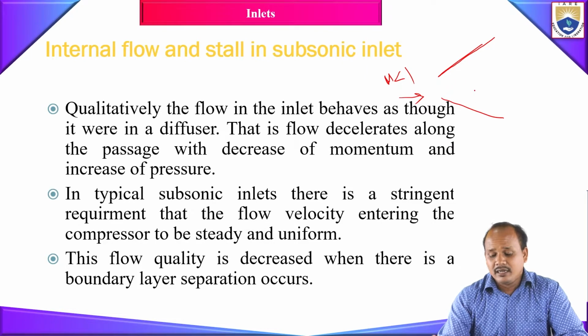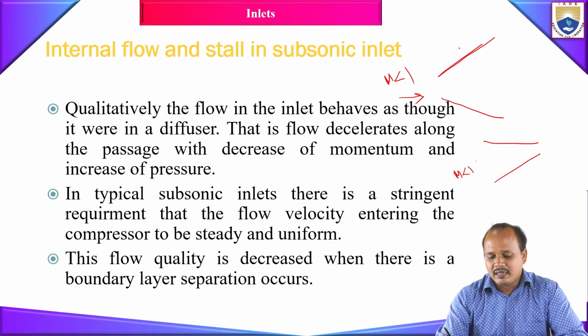So you know the area-velocity relation, right? From that, the convergent section and divergent section. For example, if I'm going to have a convergent section, this convergent section will act as a nozzle if my Mach number is less than 1. The same convergent section will act as a diffuser if my Mach number is greater than 1. Similarly, this divergent section means an increase in the area. If the passage area is increasing, that's what we call the divergent section.